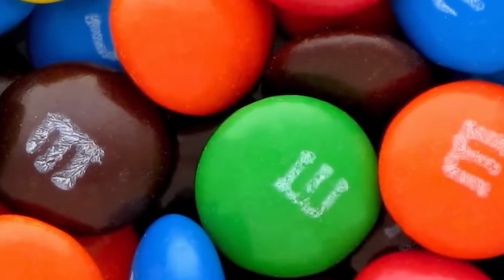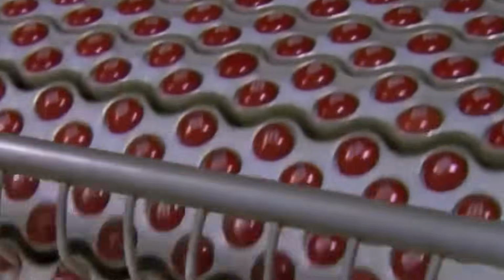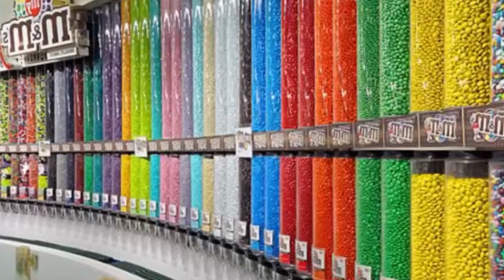Product inspection follows. Each candy passes through a vision system using a series of high-resolution cameras and 360-degree rotation to check for shell defects, discoloration, incorrect sizing, and incomplete polish. Any non-compliant unit is removed from there, streamed via pneumatic nozzles, and collected in segregated bins. Rejected items are logged and analyzed for trends in production issues, triggering upstream corrective actions if thresholds are exceeded.